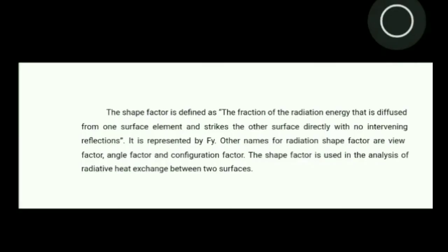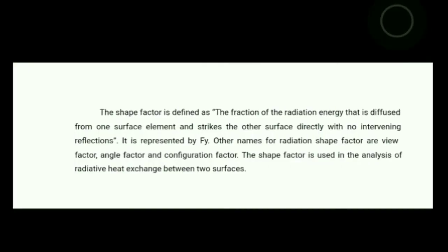Here the shape factor is a fraction of the radiation energy that is diffused from one surface element and strikes the other surface directly with no intervening reflections. The other names of this shape factor are view factor, angle factor, and the configuration factor.